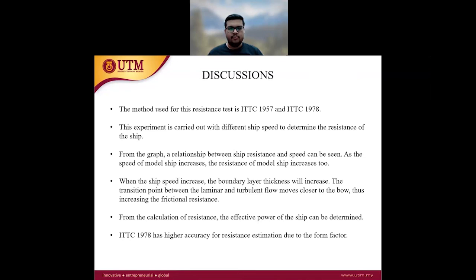To compare both methods, it can be said that ITTC 1978 has better accuracy for resistance estimation. This is due to the fact that ITTC 1978 has a form factor.